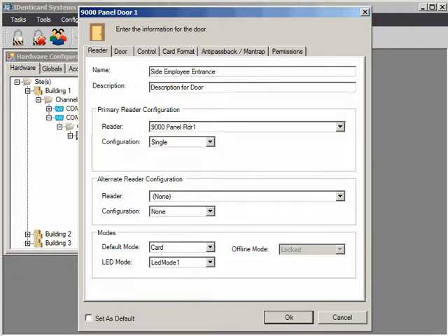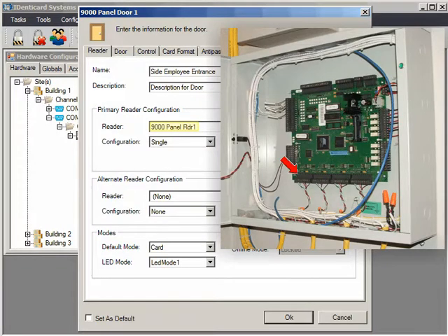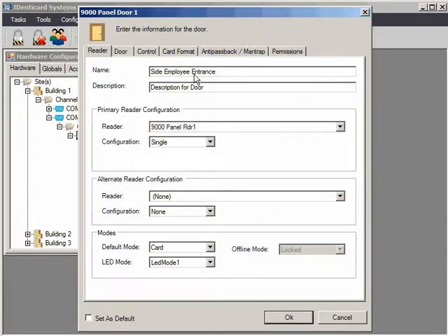A device code off a CAD drawing may be important. Enter it in the description field, or use it as a prefix to the door name. Premises assumes the first door uses reader 1. If you have in and out readers for soft or hard antipassback, use this setting. In and out readers count as 2 doors towards your maximum, not 1.